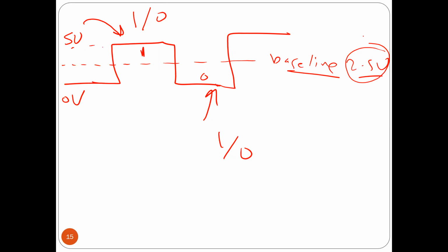Why can you not do it this way? Simply because the signal I'm going to receive is not going to look like this signal, because of the noise. You got what I'm saying? If the signal were like that, I wouldn't have any problem. I'd compare the voltage I receive to 2.5: above is 1, lower is 0. My life would be easy, but it's not like that.